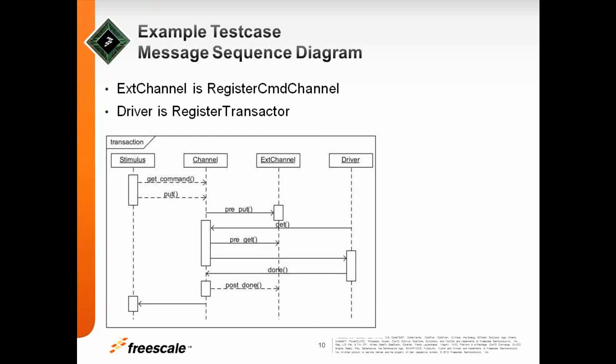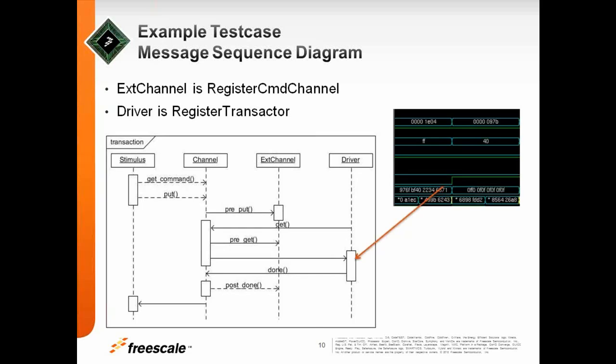And these are, in essence, the calls that are happening during your way down to execute one transaction on the stimulus side. Again, the driver is, in essence, extended from our base class, and also the channel is an extension of the command. Good. On the left-hand side, you see then the actual waveforms that this driver is generating. And now I try to go through the course of how transactions get into the game with this infrastructure.